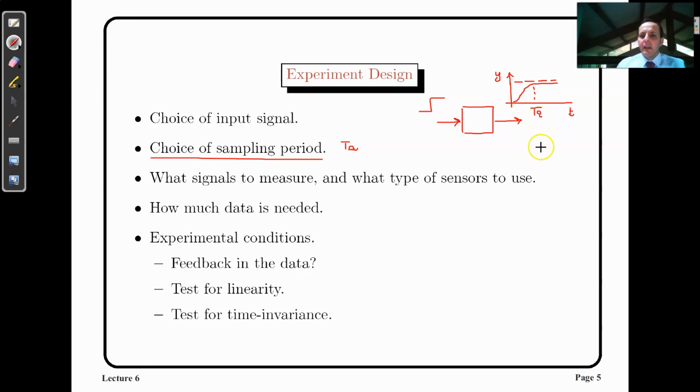So it's very simple. You don't need any acquirement, any frequency tool. The sampling period is very simply equal to the settling time divided by some factor. The smallest choice is settling time divided by 100. This is a very simple and rough selection of your sampling period.